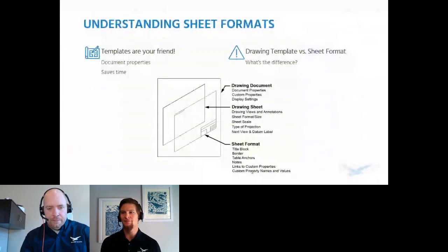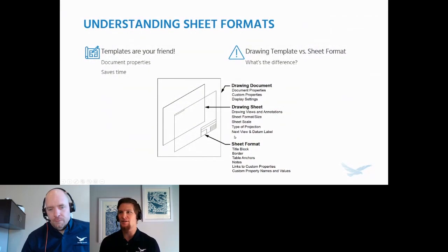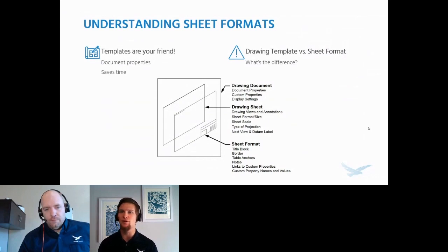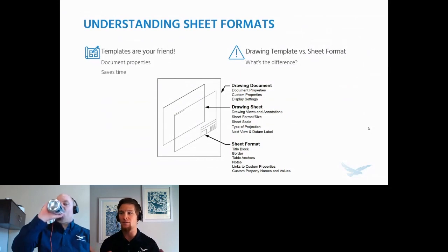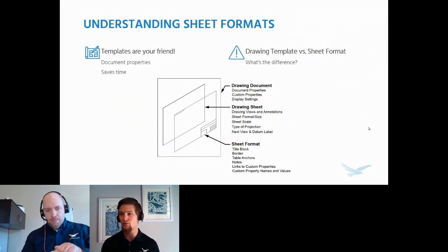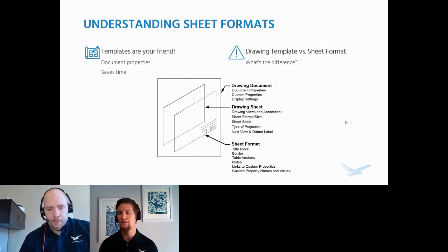Yep, exactly. Get that stuff set up as your standardized format. That's the biggest thing that I really did not understand when I started doing some SolidWorks drawings. What is the difference between that template and the sheet format? Really, a good way to think about it, and I think originally I learned this from you, Garrett, is to think of that sheet format as a layer that lives on your drawing sheet, right? You're going to have that piece of paper that contains whatever it is you want to put on it, and that sheet format is just a layer that lives there and contains certain things.